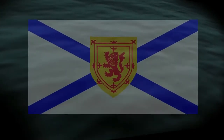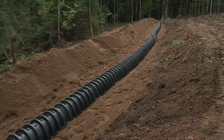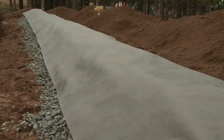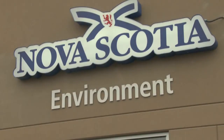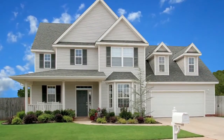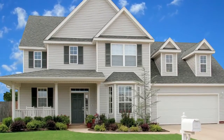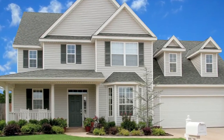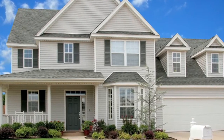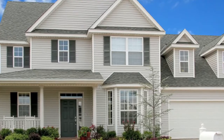In Nova Scotia, anyone wishing to construct an on-site sewage system on their property is required to have a qualified person assist them in selecting or designing a system and obtaining a Nova Scotia Environment's approval to construct an on-site sewage system. A qualified person 2 can select a system for a home with up to 4 bedrooms, while other types of dwellings will require the system to be designed by a qualified person 1, who is an engineer. All systems must be installed by a licensed on-site sewage installer.